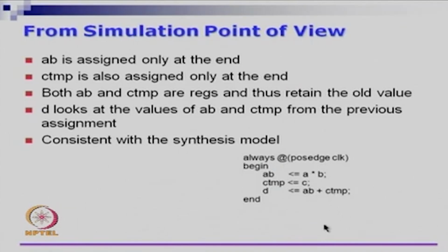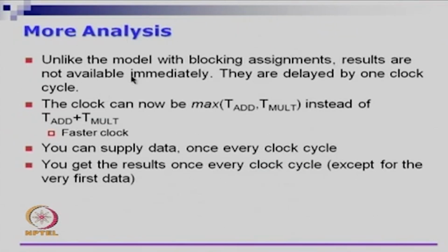in the future, and the future will come when this always block is suspended, as in all the assignments are evaluated, all the right sides are evaluated. Now we are ready to go and assign to the left sides. So, all of them will have a consistent view. A little more analysis: unlike the model with the blocking statements, the results are not available immediately. I hope that is something that you got from this week's modules.